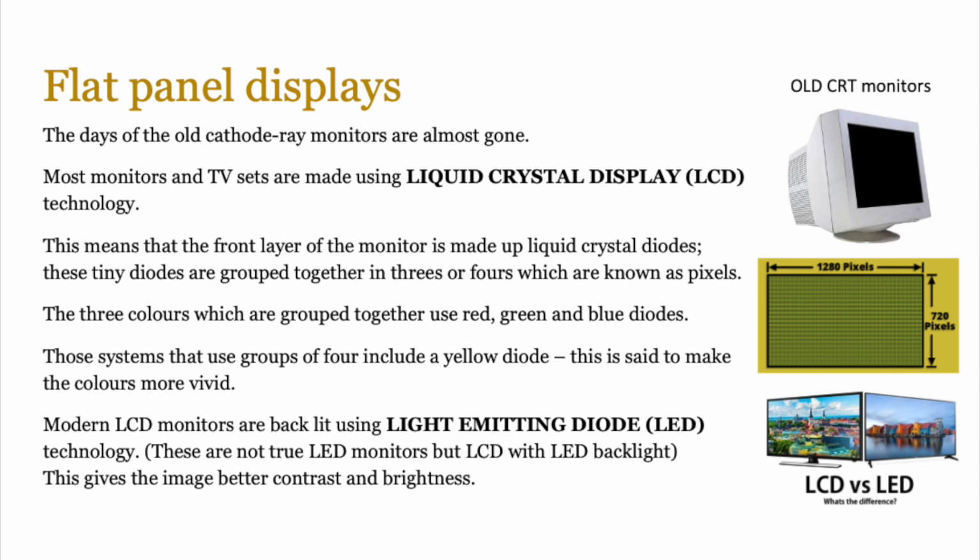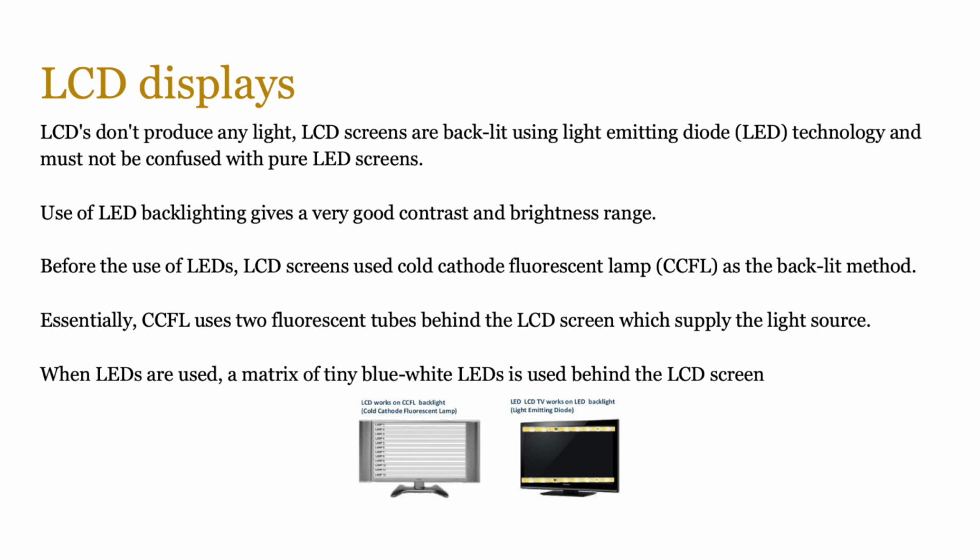Modern LCD monitors are backlit, therefore they use LED light technology, and this is not true for all types of LCD technology, but more and more these days use LED backlighting rather than a lamp-based backlighting. And the reason they use it is because it gives better contrast ratio. LCDs don't produce any light of their own. LCD screens have to be backlit using LED technology. So this must not be confused with pure LED screens. There, the LEDs themselves are the light source, so you don't need a separate light source. So LED screens tend to be a lot slimmer than LCD displays. So use of LED backlighting in LCD displays gives a very good contrast and brightness range.